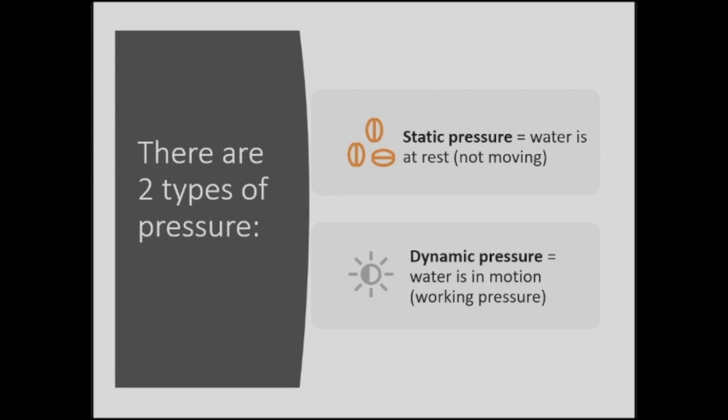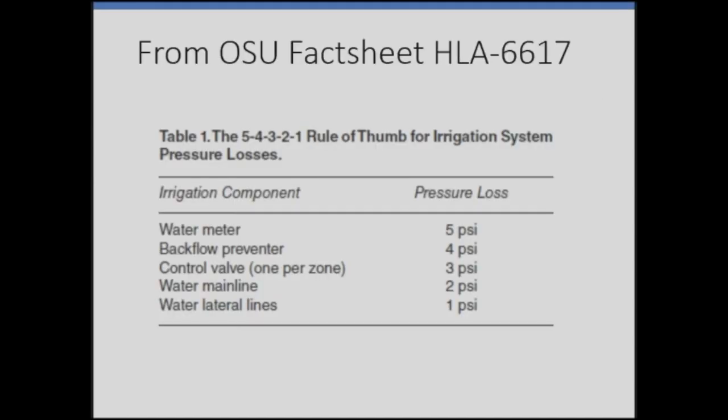Yes, sure. Yeah, so this was targeting more of a residential sort of situation, but the key thing I wanted to highlight is that when we measure, a lot of times we'll measure the static pressure somewhere where it's kind of convenient, and that may or may not be near the sprinkler head, right? Every system's going to be different.